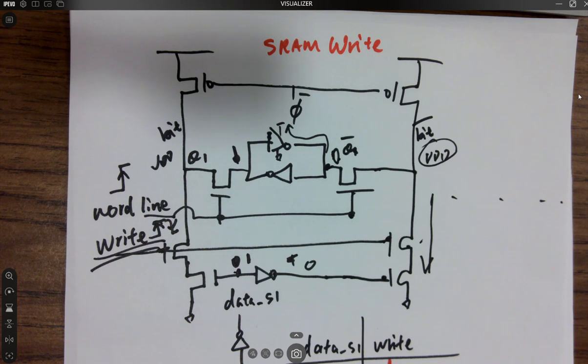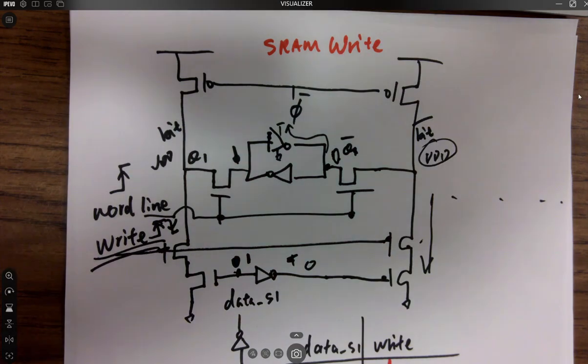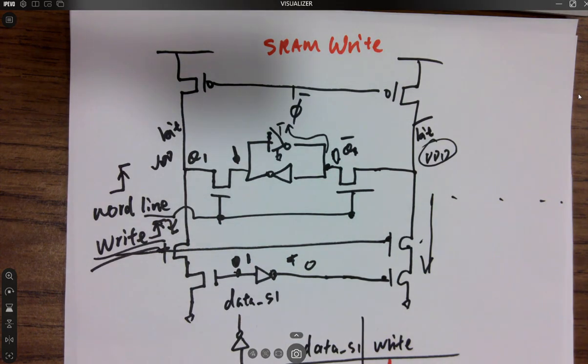When we are recording an audio signal to the chip, and we are trying to read it out page by page for the SD card, which is 512 bytes, it won't be able to handle it.